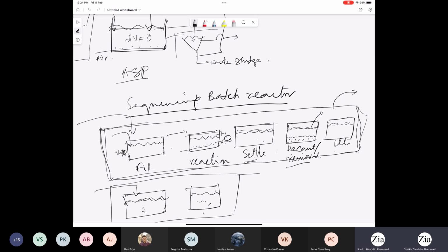So the advantage is, when you try to manage a lower volume system, you can have multiple smaller reactors. In a treatment plant, essentially you have chambers. When you go to any treatment plant with a sequencing batch reactor, they will have chambers separated by walls. Just imagine a long box with multiple separators to form individual chambers. Moving from one chamber to another is then very easy.